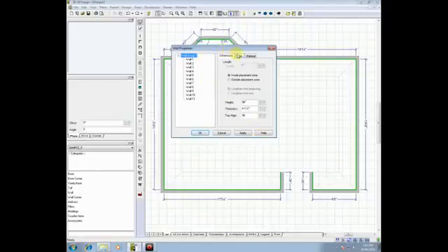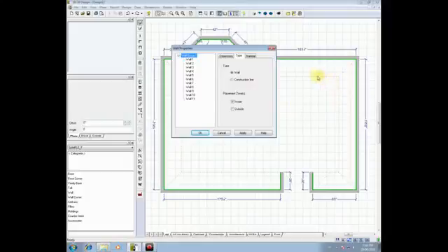Now, we have another tab here to the right called Type. What does Type do? Type gives you the ability to make walls either solid walls, or if I clicked Construction Line, it would make the wall invisible. Why is that important? If you look around your room, you see a boundary space. You see broken lines that go all the way around the room. That's your placement zone, and that's where your cabinets will be placed.